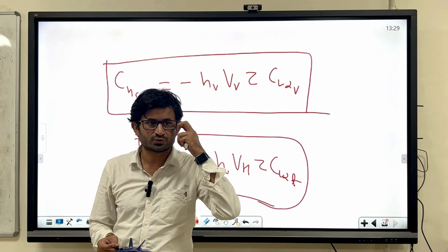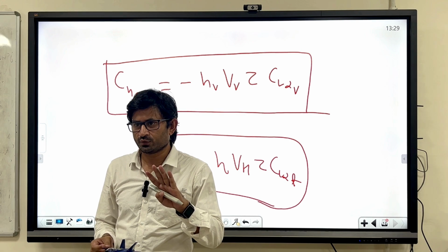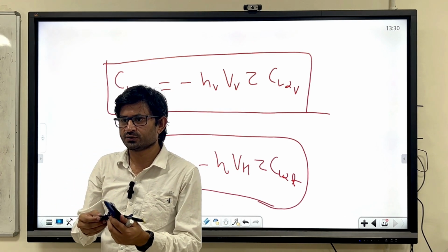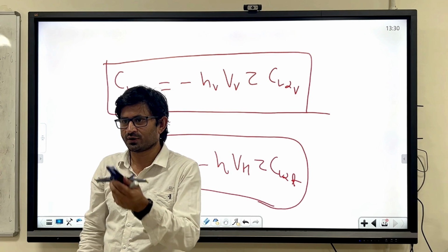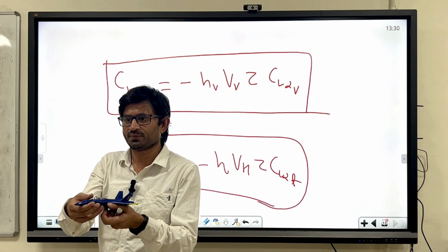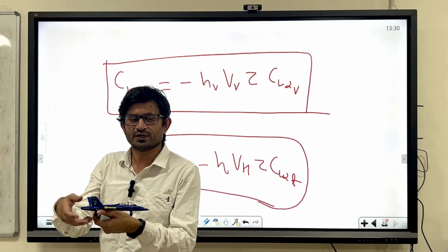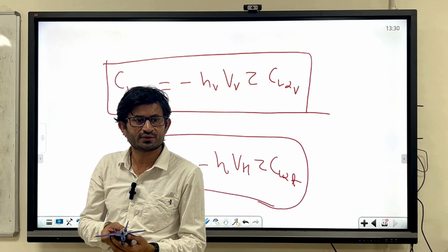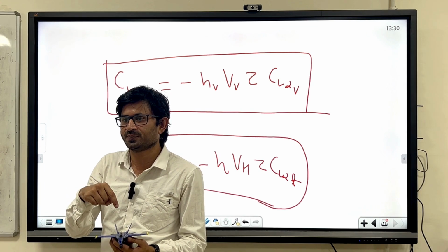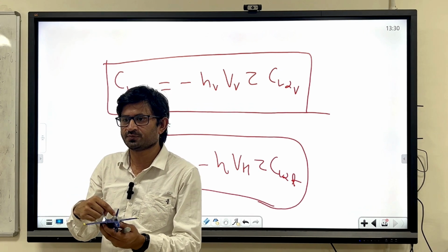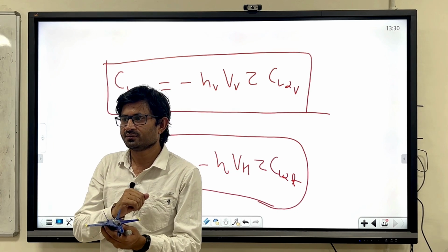Then in that case you can use the rudder. Two best uses I have told you, right? Your aircraft is stalled, so you are not producing any lift. So you are losing altitude, and at the same time you are yawing also, and that yaw rate is more than compared to the roll and pitch rate. That phenomenon is known as a spin. So in this case, to stop the spin, you can use the rudder.